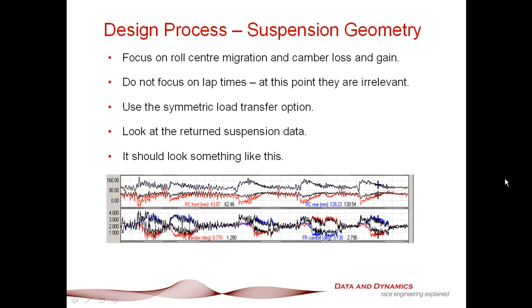Let's talk about the design process. In particular, I want to talk to you about some tips for suspension geometry. When you start looking at your suspension geometry, you focus on roll center migration and camber loss and gains. Do not focus on lap times. At this point in the game, they are irrelevant.